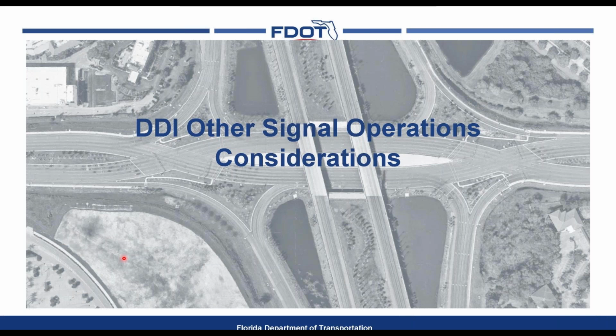So to some level, you hope that visibility will allow a vehicle to yield long enough for that bicyclist to go through. It's a similar issue we have at all intersections to some level, just because that T1 and T2, that T2 is a little bit greater. So I think part of it is just making sure that visibility is there. When we talked about the geometric design a couple of webinars ago, you really want to focus on making sure that intersection sight distance is available for those vehicles that are turning right to be able to see over their left at oncoming vehicles and bicyclists in this case. Same with the vehicles that are potentially turning left, being able to see.